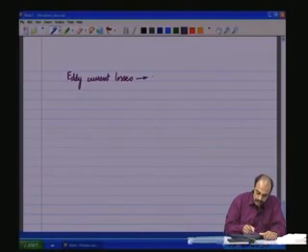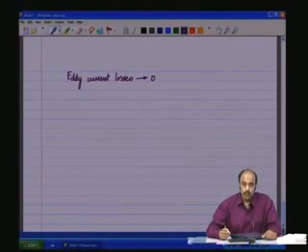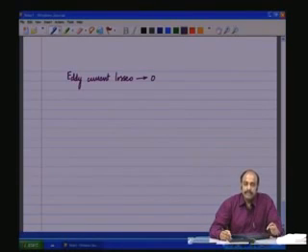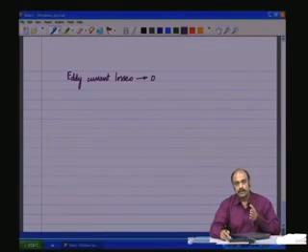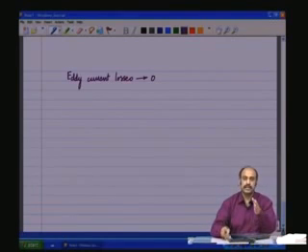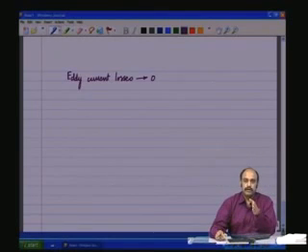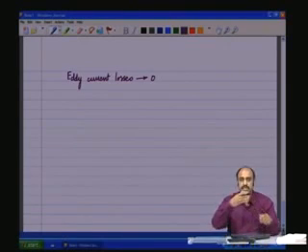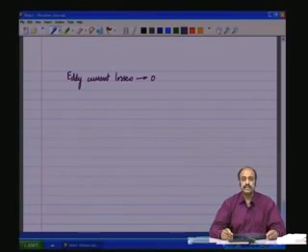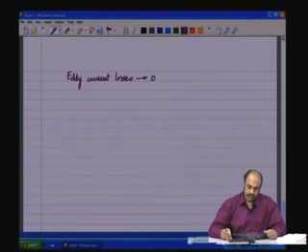Losses should also tend to 0, which means the resistivity of the core material, because if there is a flux flowing in the core material, there are going to be currents around the flow of the flux in an orthogonal plane. So, if the resistivity of the orthogonal plane is increased, then that eddy current is going to be reduced. Now, if that resistivity becomes infinite, then the eddy currents will also tend to 0.